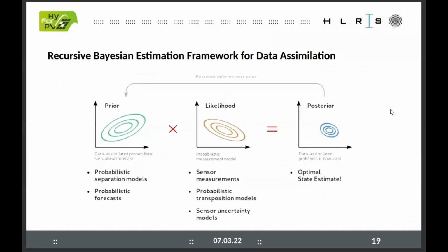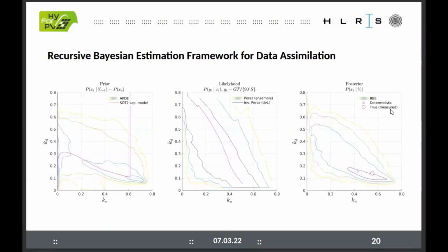If we want to get the most out of it, we have to include at least albedo and a circumsolar component. Otherwise, we will not really realize the improvement in accuracy after the transposition model that we hope to see after this. Another issue is performance.